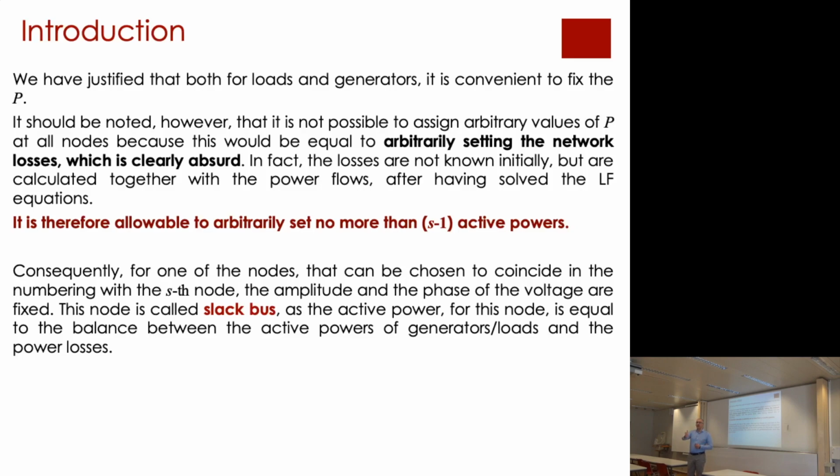It means that all the phases of all the other phasors, currents, voltages, powers, and whatsoever, are referred to this guy, to the slack. Okay? This is how we traditionally formulate the external constraints in the load flow problem. Okay?